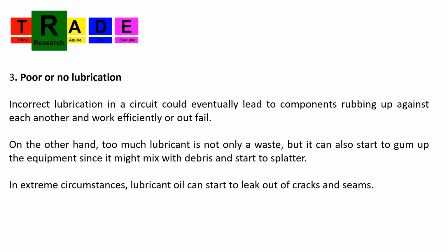Are components in the circuit rubbing metal to metal? Am I using the correct oil in my pneumatic circuit? Is the incorrect oil, or the oil that I'm using, corroding the seals and creating a bigger problem? Always use the oil or lubricant specified by the OEM component manufacturer.